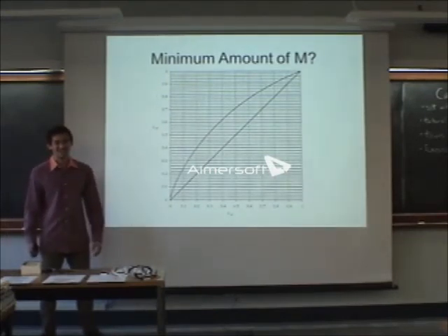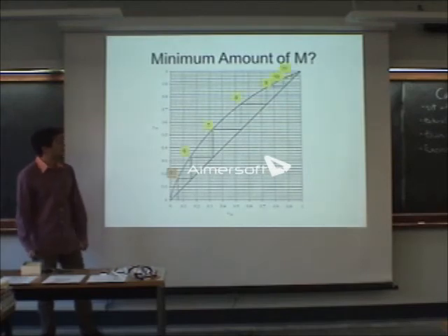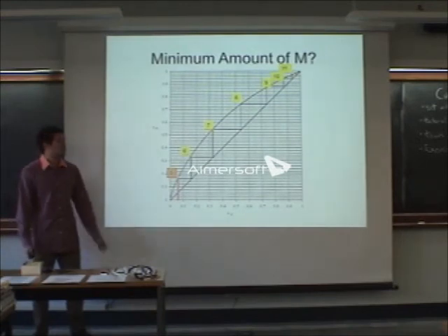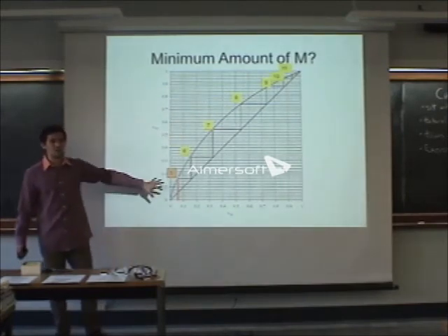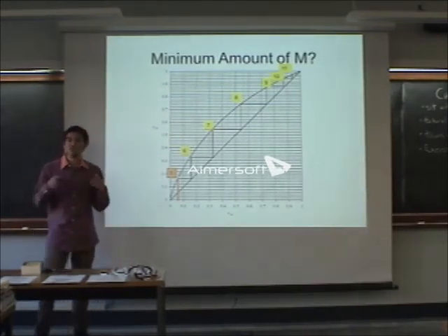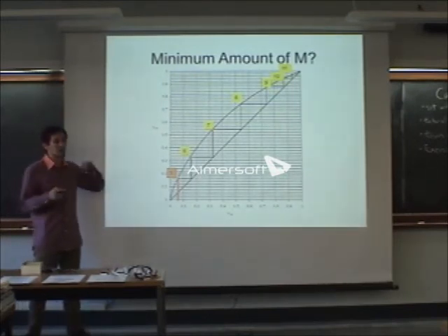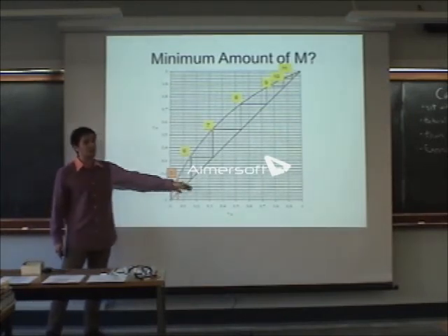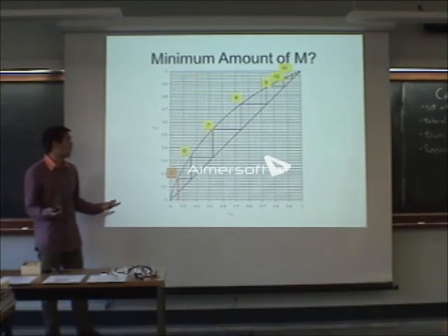Shane? You increase the slope as much as possible. The slope of the stripper should be very high. Okay, so actually, ignore the stripping section, we're just going to focus on the rectifying. The rectifying section is what's going to achieve your 98% tops, not the stripping. And the question asks, what's the lowest percent of N out of the reactor that we can achieve the top separation of 98%? So I'm not even going to look at stripping. I'm going to run the rectifying section at total reflux, so the slope of the operating line is just going to be the XY line, slope of 1.